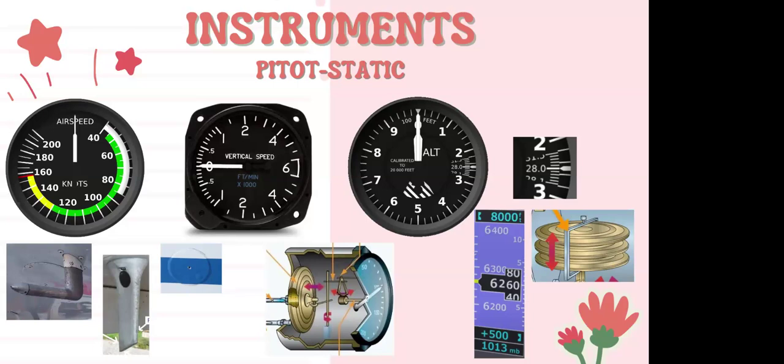So if you're doing your cross-country flights or even flying from one airport to the next, you always want to get that weather, not just because you want to make sure you're not in a 12-knot gusting crosswind, but also because you want to make sure you're operating on the most recent altimeter setting, because it can vary even airport to airport. If you went from McClellan to Mather, which is a short 8 miles away, we could have a slightly different barometric pressure. So you want to make sure you are always being vigilant about that.